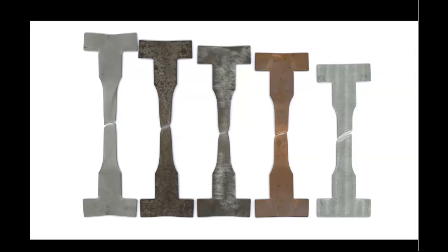So as engineers, please be mindful that steels could be superior, not necessarily all, but they could be superior to non-ferrous metals in terms of ductility, necking behavior and general ability to withstand high force, and actually cope with a lot of deformation before breaking. That's why steels are used in the majority of engineering components, simply because they're quite forgiving to abuse.